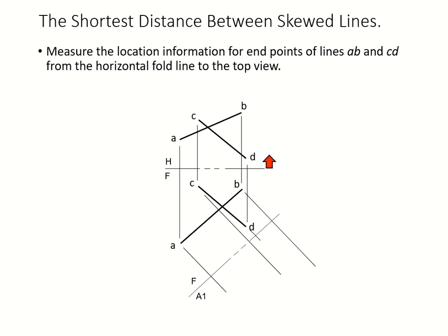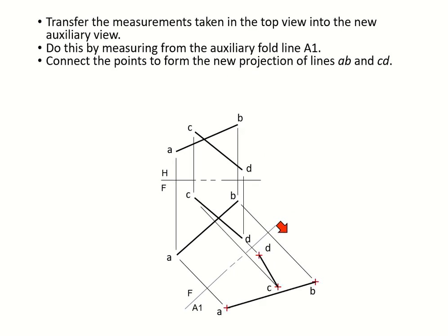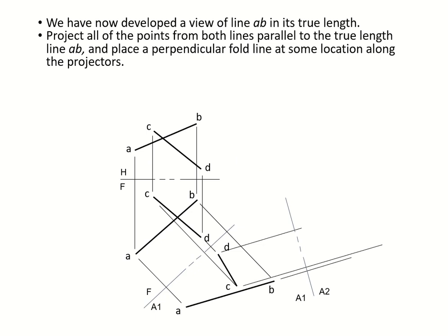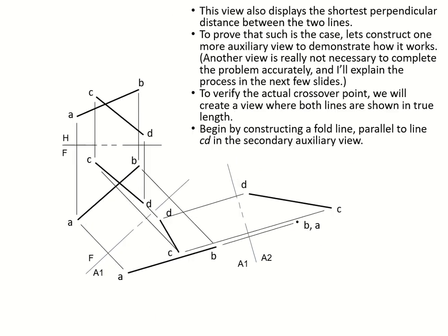Go all the way back again to C. So start with fold line, direction, measurement, another fold line, directions, measurements, connect all of it, okay? That's how we end up getting our right side view, yes? So this is your first primary auxiliary, and second, which is your secondary auxiliary, okay?